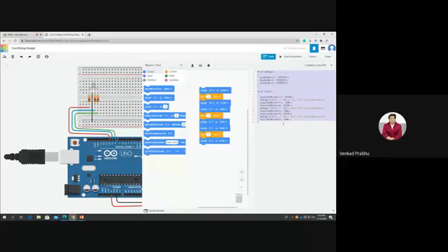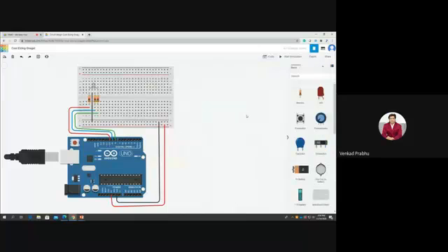This will execute with that real device, Arduino board, with the breadboard, with the RGB LED. If you have given the connections, and if you connect that Arduino board with your laptop, then just copy and paste this code in your Arduino IDE, then execute. It will work fine. So this is the power of this TinkerCAD. We can make mistakes, learn, correct them, and then we can go to the real device.